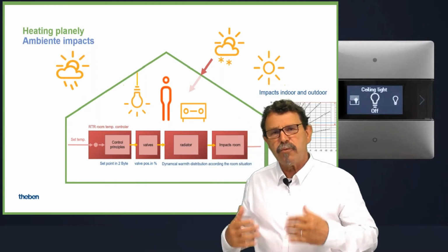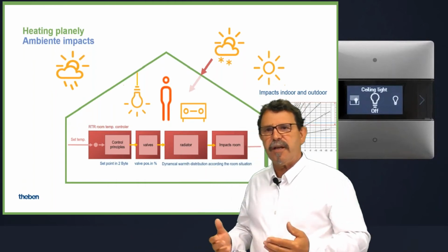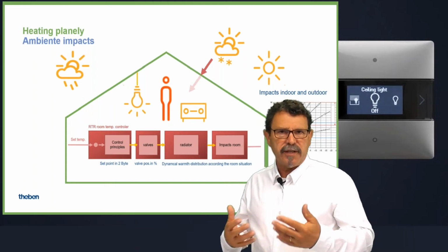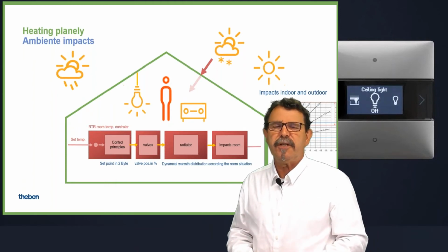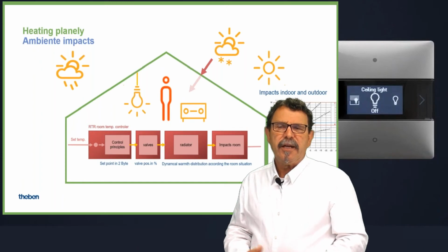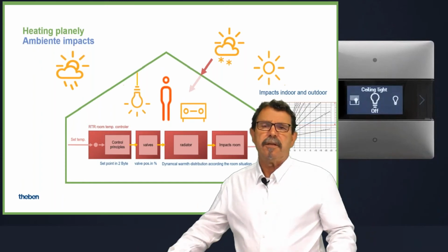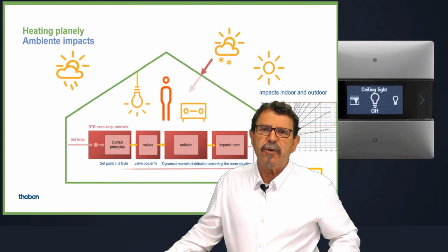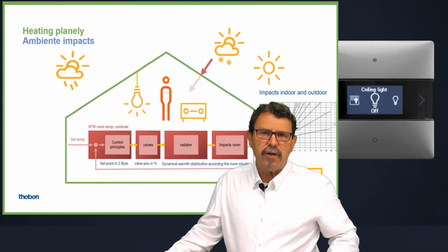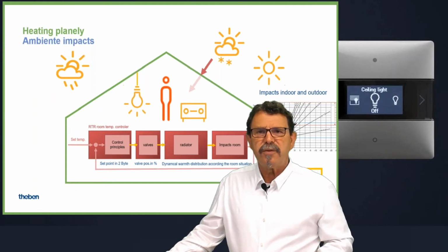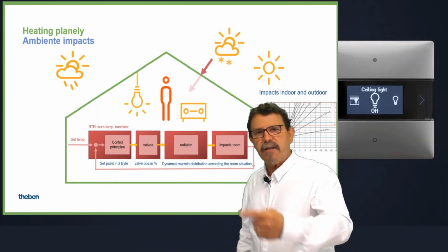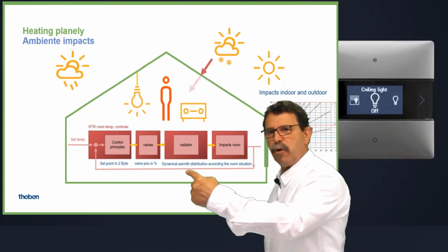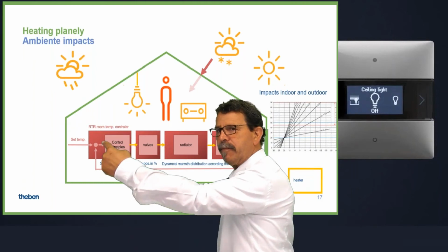And the room temperature controller calculates the valve position, or the heating activating valve value, accordingly, giving it to a valve, for instance a motor-driven valve, to open or close and give the reasonable warmth into the room. And this cycle is permanently running internally.